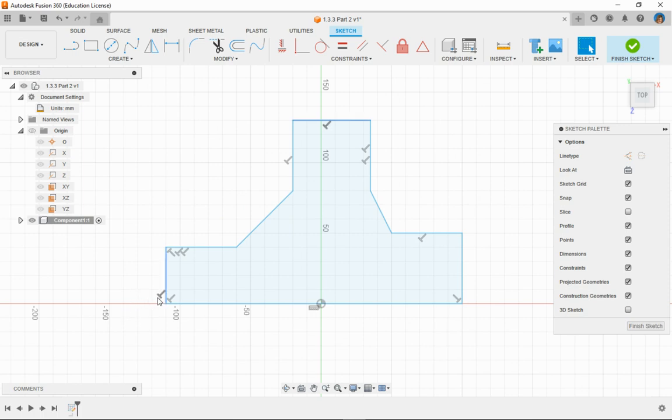For example, when I hover over this perpendicular constraint, I can see that the perpendicular constraint on the top line also highlights. So that means they go together. So you need to find a way to show which perpendicular constraints go together. It looks like in this case, all I have is perpendicular and then I have one horizontal. So you do need to draw however yours came out. You're not drawing mine. You are sketching and then you're going to hand sketch your Fusion sketch into your notebook.